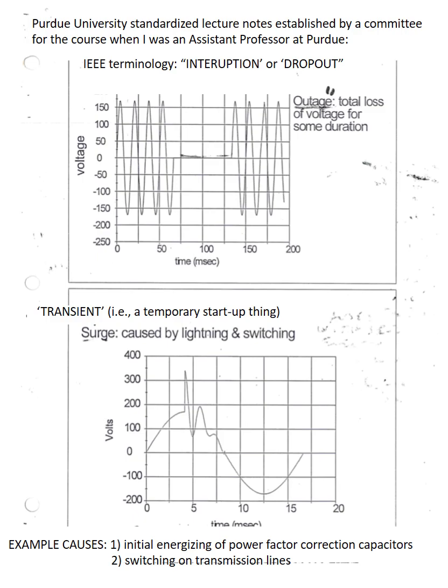Because what happens is your voltage and current get out of phase with each other and mess up the delivery of power. And the power factor is an angle between the phasors that represent the two sine waves of the current and voltage, the angle between those two vector representations, phase representations of the sine waves. So if you understand sine waves and phasors in current and voltage, that makes sense to you. If not, don't worry about it.